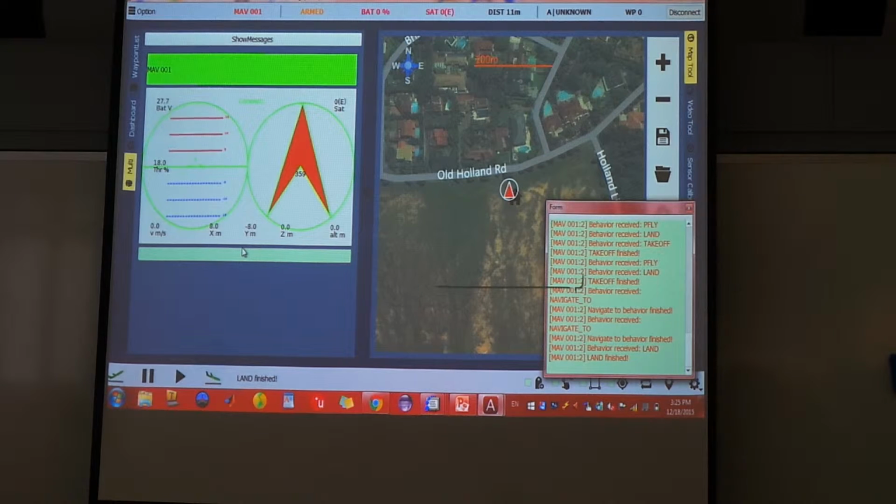My question is, how fast do you sample your data? For example, your ultrasonic sensor. This distance sensor is quite tough, and it's not ultrasonic, it's a laser one. Laser, yeah. This one, the sampling rate is 1000 hertz. But the sampling we are taking for the filter is 20 hertz. 20 hertz. So for the other sensors, also 20 hertz.